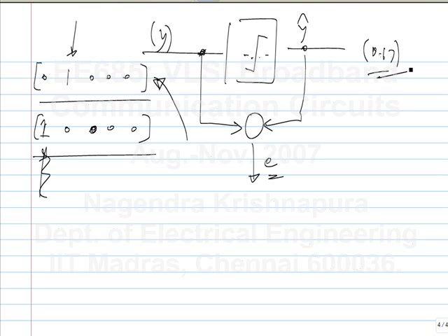Okay. So in these cases, what you need is, that's why you need training, right? In that case, you know what bit pattern you are sending. So you can compute the error with respect to what was actually sent, not what you sliced. I think that is probably what is happening. Maybe I thought that 0.5 was close enough to 0.67 and it will behave similarly, but apparently not.